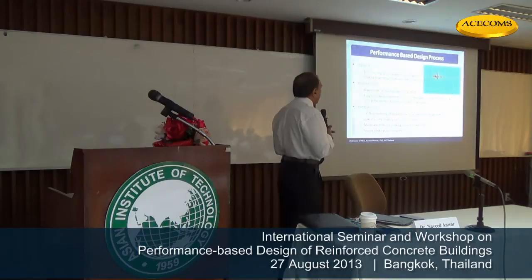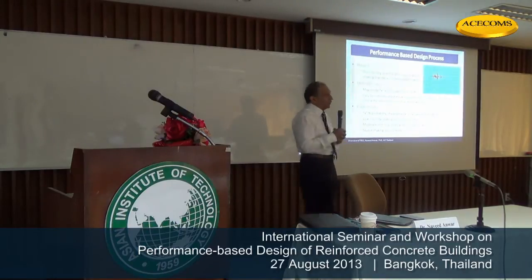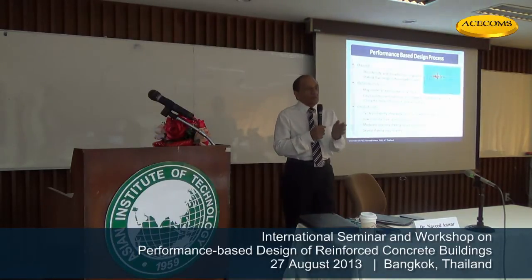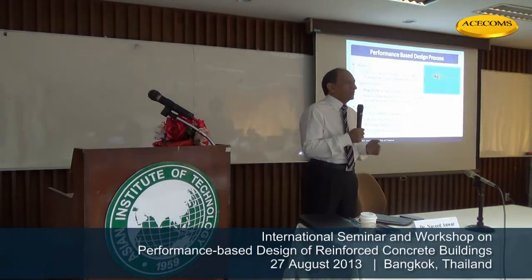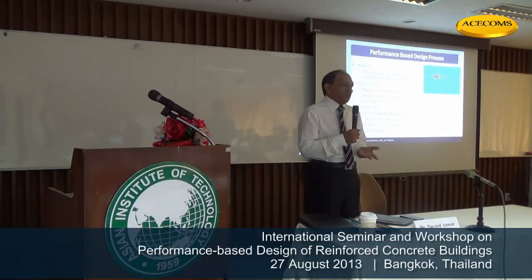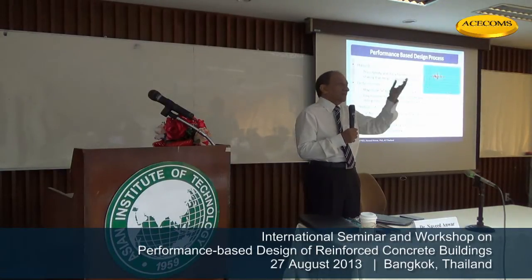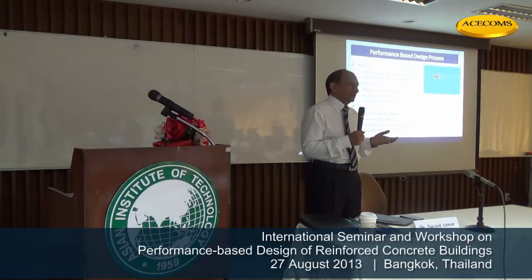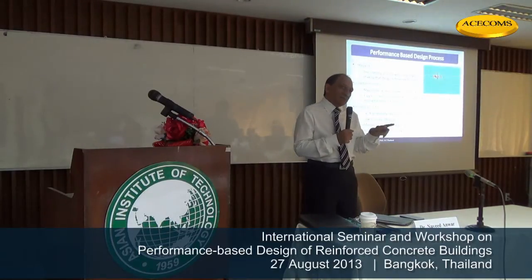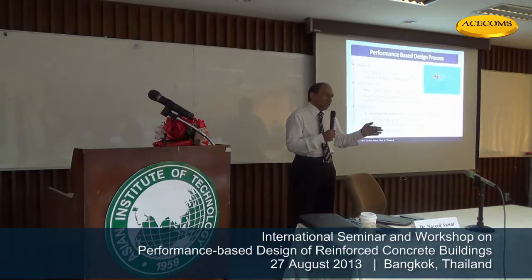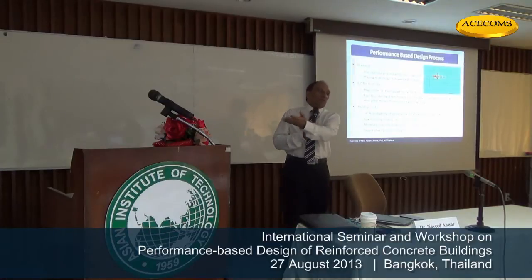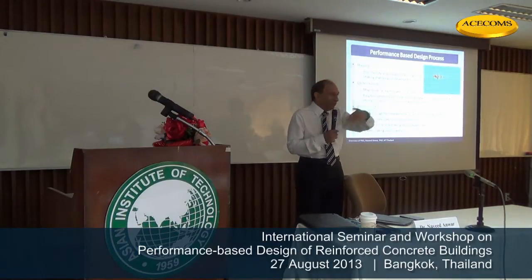So the event, we can say that we are talking about the probability that a certain level of earthquake will occur on a certain fault, or we can say a certain level of earthquake will come to this site with this intensity in a certain number of years. Doesn't matter where it comes from. So two different things. One is that a fault will rupture or crack, let's say in 1,000 years, and has the capacity to generate a magnitude 7 earthquake. Okay, that's good. But my building is somewhere else, and my building may be affected by many faults.